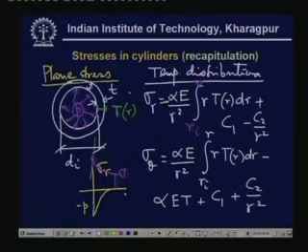important, because normally the pressure vessels should carry some liquid or some gas, some material at very high temperature. For example, in the boilers it is expected to carry the liquid at high temperature. So, when the temperature distribution is uneven through the thickness of a thick cylinder, the thermal stress may be developed, and that has to be taken into consideration while designing. So, these are very important things. Now, this is what we have already learned.